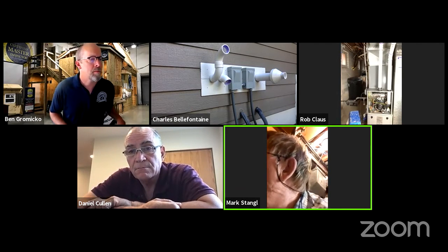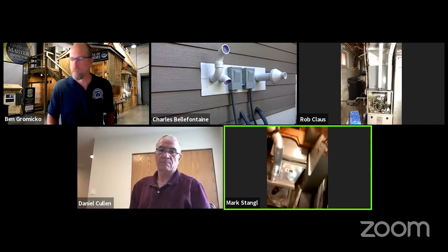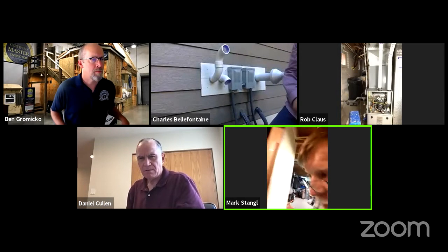But one other thing that is good to do, I'm turning this off now, is that when the system shuts down, sometimes you'll have backflow of carbon monoxide come down into the chimney and exhaust into the heating room. And you get some indication of the efficiency and the performance of the chimney and the blower system once that happens. And it's going to shut down. And now it's going through the cooling cycle.